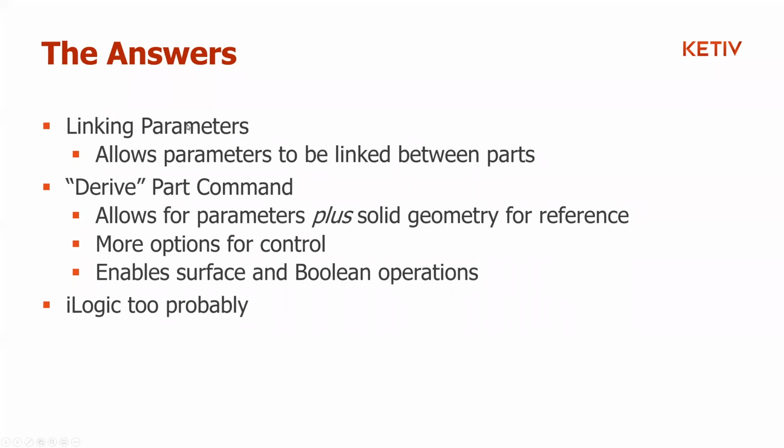We could, of course, do the linking parameters stuff, which I'm going to start with myself. Linking parameters allows you to specifically just take parameters from one part and put them into another part to be used like your regular parameters. I'm assuming you guys are all familiar with parameters as well at this point, but let me know if you guys need a refresher on that.